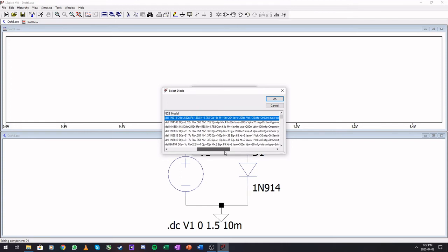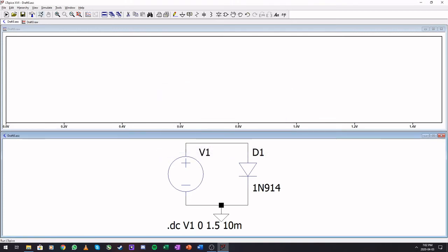So you can go and look in the model or in the SPICE model of a data sheet where this diode breaks. You will not break it in the simulation. Okay, so always be mindful that it's going to simulate perfectly no matter how you increase that voltage, it will still work.